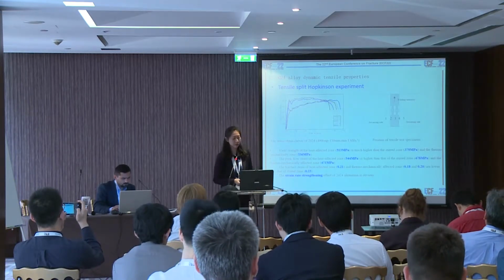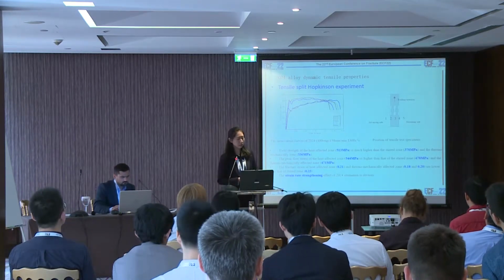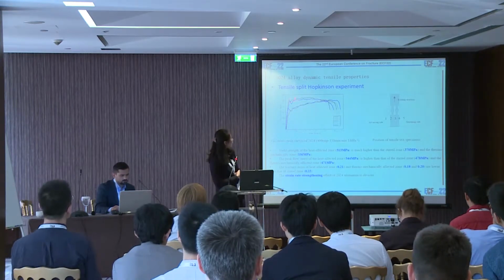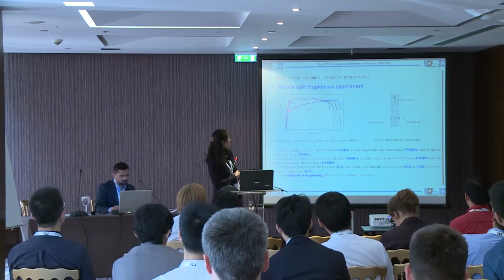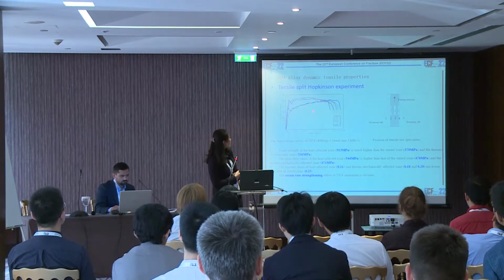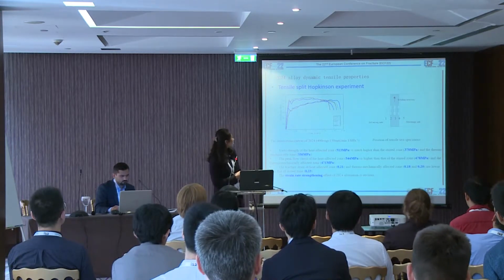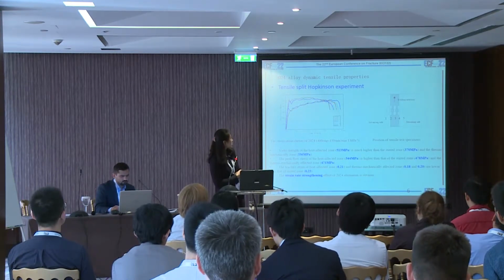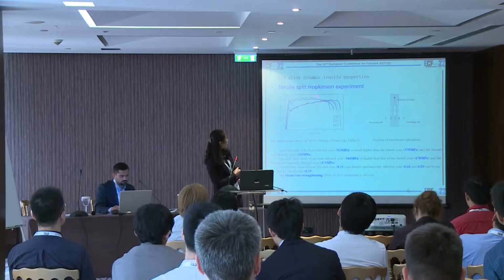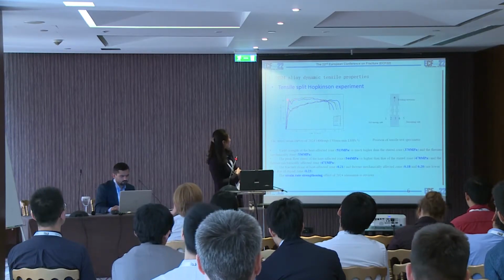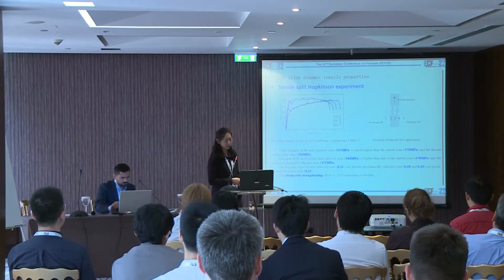And these are the stress strain curves of the 2024. We can see that for all of the 5 curves, the yield strength here, these 2 curves are the heat affected zone, is higher than the other 3 samples, and the peak flow stress here and here is also higher than the others. But the blue curve, which is the stirred zone, shows the highest ductility. And for all of the 5 curves, the peak flow stress is higher than the yield strength. So we can see that the strain rate strengthening effect of 2024 is obvious.